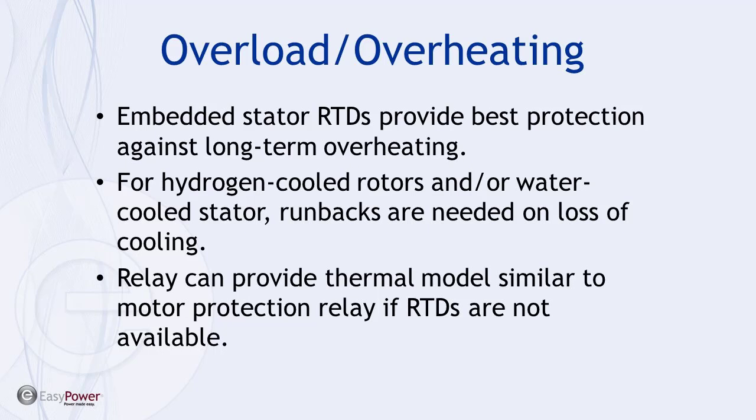Generator overloading or overheating, the best protection there is really going to be embedded RTDs, temperature detectors in the stator, and to provide alarm and tripping for those. And if you have water-cooled stator or hydrogen cooling, you're going to need some runbacks, automatic load reductions or trips, if you lose those modes of cooling.